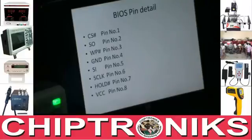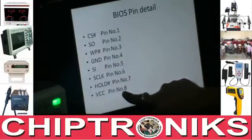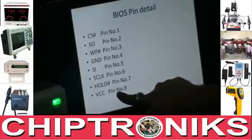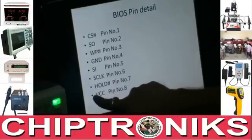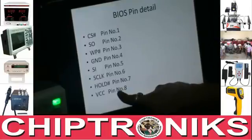Now if you need to check whether the BIOS is faulty or in good condition, or whether it will work or not, you need to check VCC pin number 8, because this is the main input voltage pin. Here we need an input voltage of 3.3 volts.